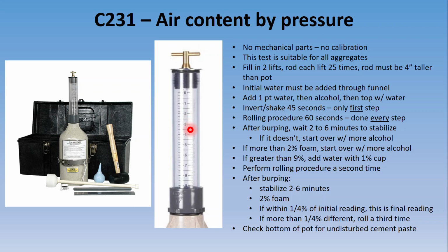If that water level doesn't stabilize within 6 minutes, the test is invalid, you start over, and you add more alcohol. That's going to be the answer to a lot of these if or if-then questions: test is invalid, start over, add more alcohol. So that's the first reason why you would have to start over, that the water level did not stabilize after 6 minutes. If you see more than 2% foam in the neck at this stage, you also have to start over and add more alcohol, right?